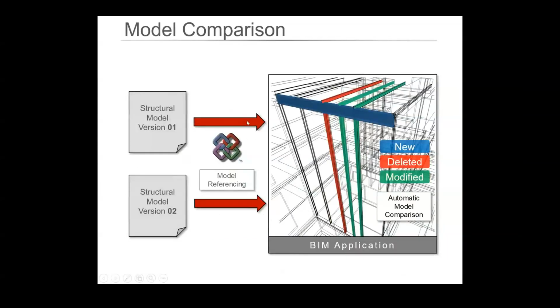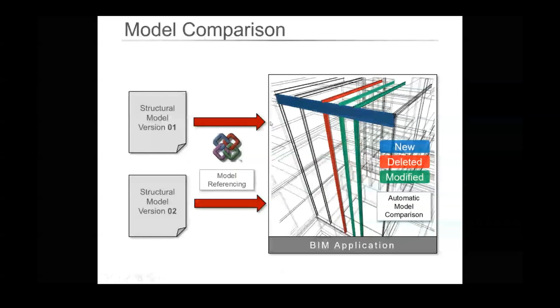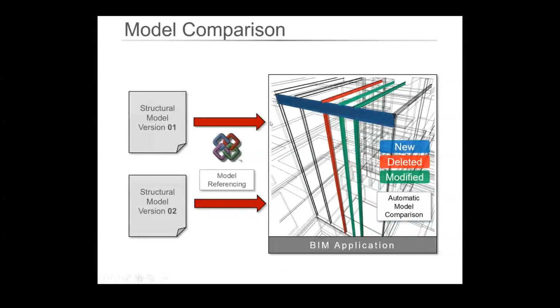And then the model comparison, so we can compare versions. So if we have made some changes and we want to compare the difference between last week's model and this week's model, we can bring them together in the same authoring software like Solibri or whatever, and check where the differences are and see what the major changes have been.